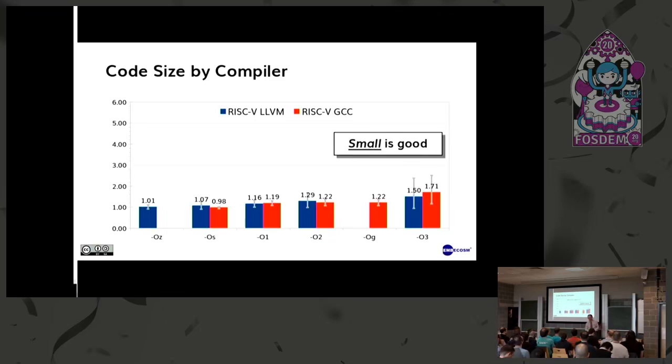The reference platform happens to be the code size of RISC-V IMC run with -Os using GCC 9. Okay? That's actually going to change for the release. The reference base architecture will be Cortex M4, but I'm using what we've got today. And you can see there are little bars. Those bars are a single geometric standard deviation up and down. Okay, and you can see that this is close to the reference. So this is the reference for size -Os. Okay, and the error bars are quite small. Up this end, they're quite big.